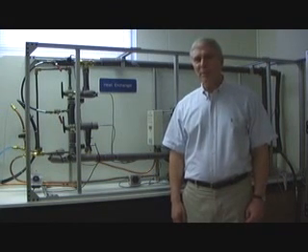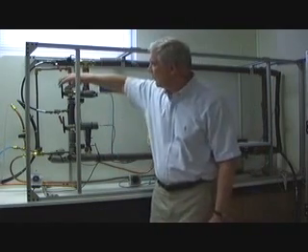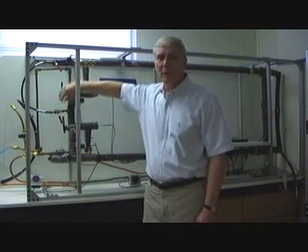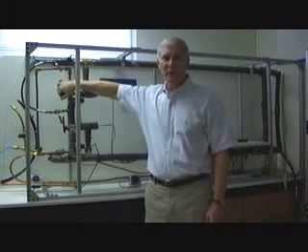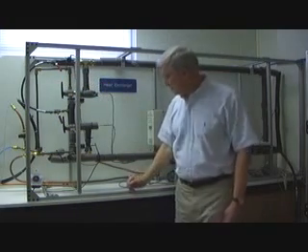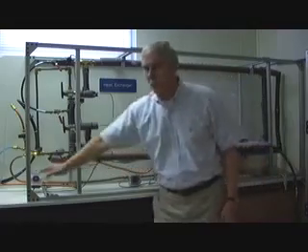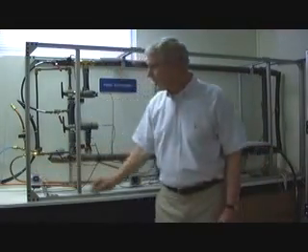This is our double pipe heat exchanger. It can be set up to operate in either the counterflow or parallel flow configuration. The configuration is set up using these two valves here, which are labeled counter and parallel flow. The arrows point to the correct direction. Flow is measured using two rotary flow sensors, one located here, one located here.